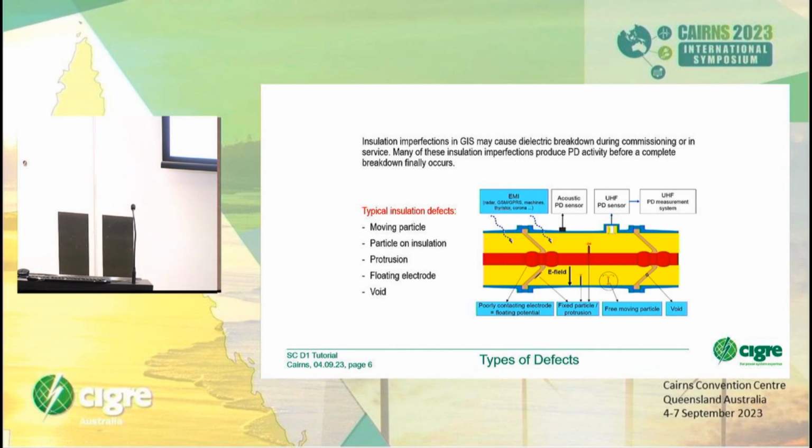So, sulfur hexafluoride. Nowadays we have a few prototypes already running with SF6-free gases. We call them alternative gases, based on dry air, synthetic air, or on fluoronitriles or fluoroketones, but it's still under investigation. We have some epoxy spacers, which put the conductor in the center, in the middle of the gas compartment, to fix it there.